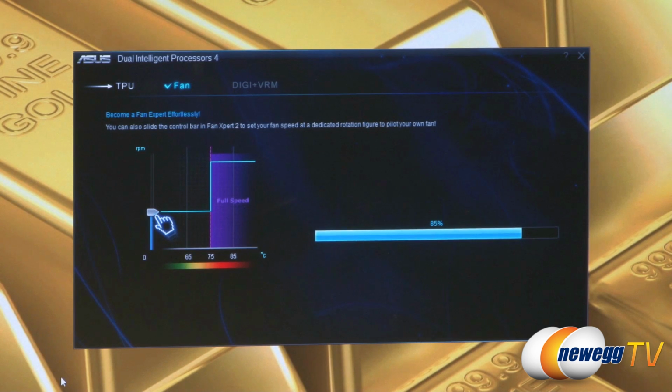Once that information is stored, you can quickly go into the Fan Expert 2 software, and if you want to hit silent, the fans will go to their minimum operating value, which is essentially off, so they'll really be silent. And when the CPU ramps up, they'll be much more moderate and quiet, because they know exactly the maximum range of operation. In the same way, you could set it to a standard profile to keep a good balance of improved thermal performance while still being moderately quiet. And then you could go to higher performance by just disabling it outright, because it knows what the maximum value is. So overall, you're automatically tuning your system and having that flexibility.